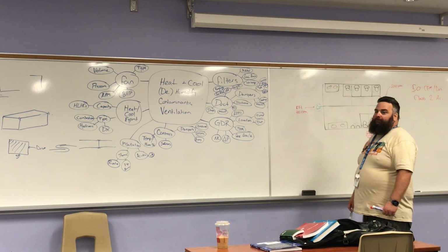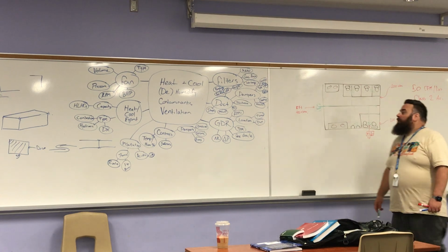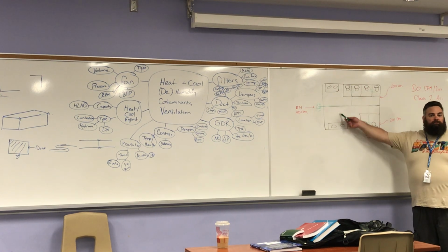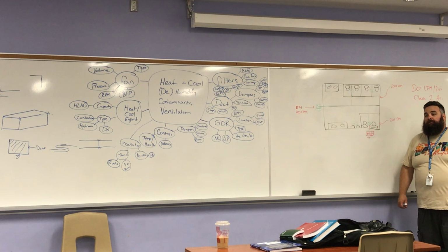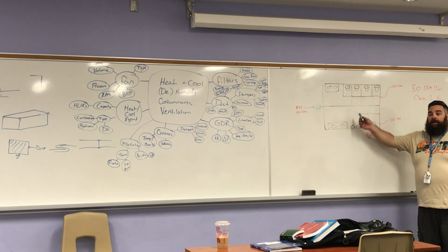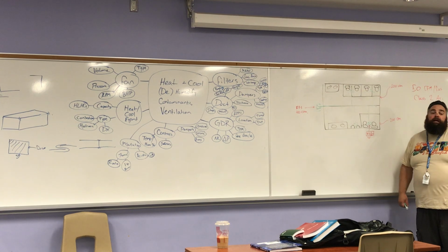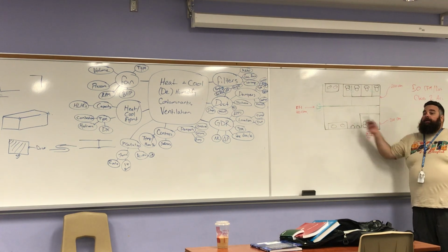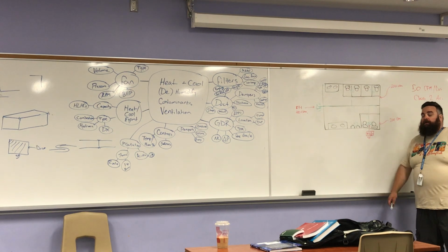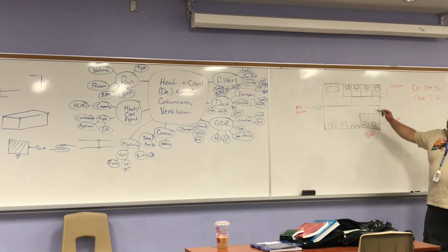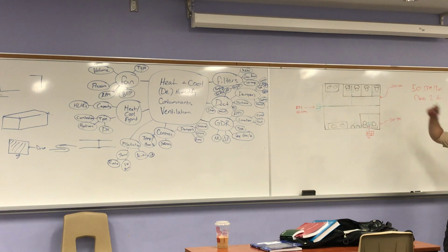What else? Oh, the bathroom that we're exhausting, is that the only air that's gonna be done? Also other ductwork. Presumably, we wanna add heating and cooling to this space. That might be air. We might just put baseboard electric heaters, but we might have other ductwork to contend with. So I can't always do it as simply as I want, but in this case, it's my example, so yes, I can.